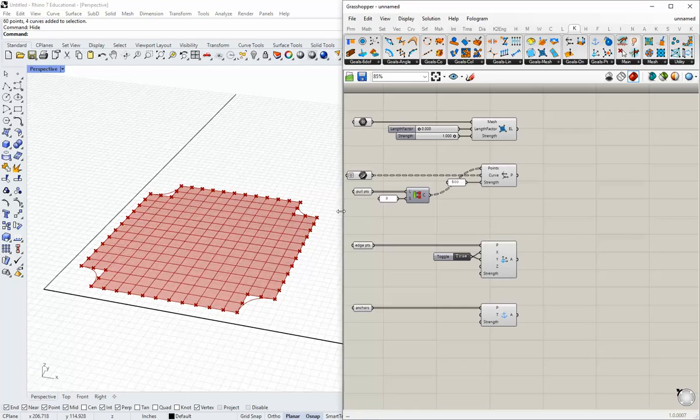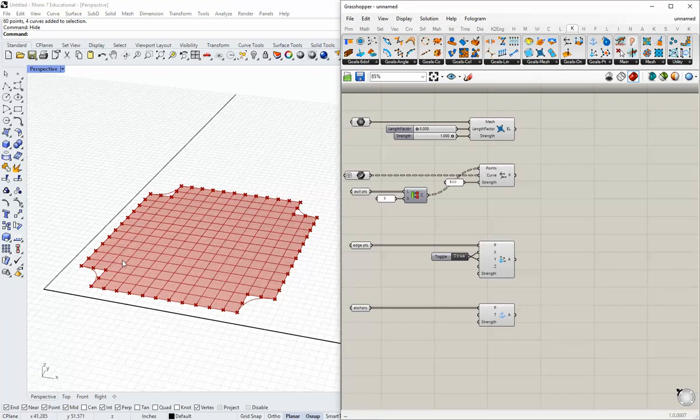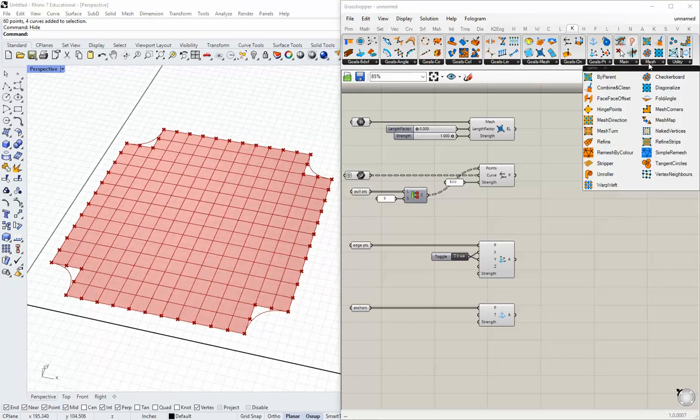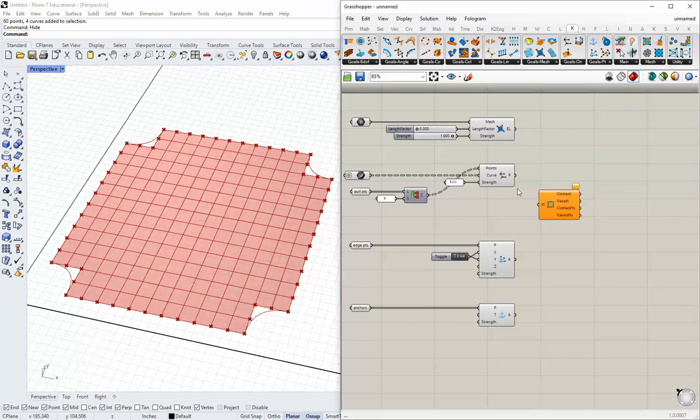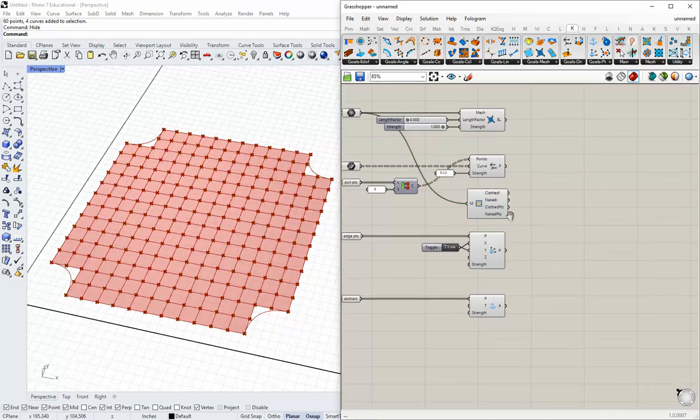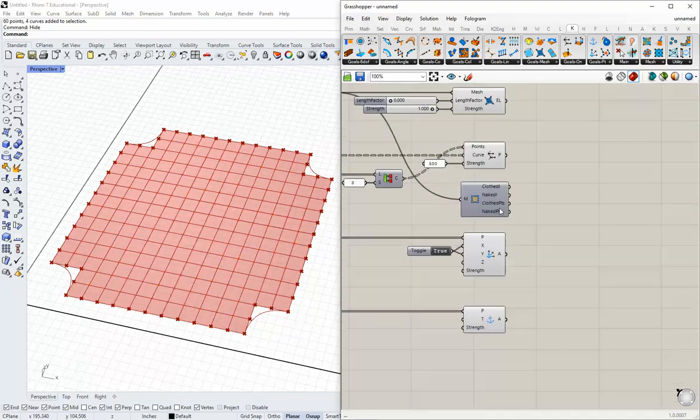What I want to do then is add basically a unary force, or an upward force, to the points that are inbound on the mesh. So let's go over to the mesh box over here in Kangaroo and grab the naked vertices component. We're going to use our mesh to find this data. I guess we'll put it here. You can turn that one off so we don't get any overlapping previews.